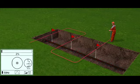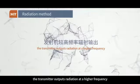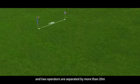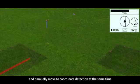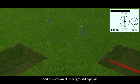When the radiation method is used for detection, the transmitter outputs radiation at a higher frequency. The receiver is tuned to the same frequency, and two operators, separated by more than 20 meters, move in parallel to coordinate detection at the same time. Observe the variation of signal to determine the position and orientation of the underground pipeline.